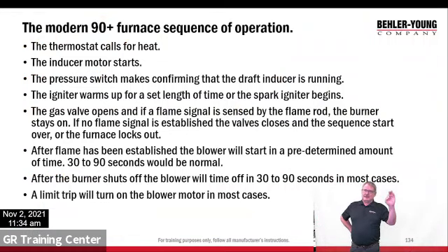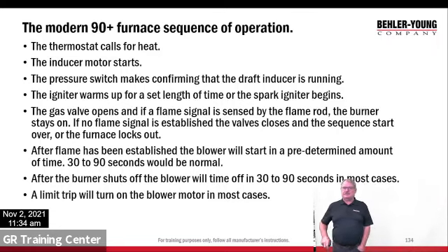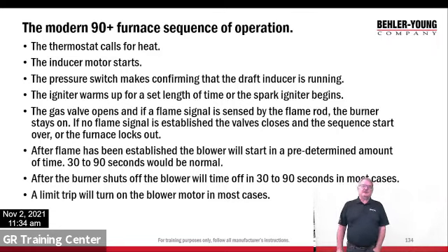We have another set amount of time that it's going to allow the flame rod to prove the flame. If it doesn't, locks out. After flame has been established, after, again, a predetermined amount of time, between 30 and 90 seconds, the blower will come on. After the burner shuts off, on time again, the blower will shut off. Most cases, a limit trip now will turn the blower on. All right, so that's pretty standard on pretty much everything.